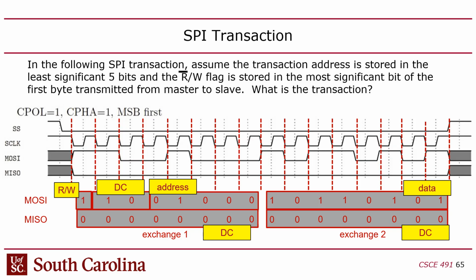In other words, what I'm trying to say is that the ESP32 hardware only knows how to do exchanges. It doesn't know how to do transactions. The transactional behavior is part of the driver, essentially, in the software. It's determined by the software. So the transaction is a software behavior. The exchange is part of the hardware behavior, unless you're bit banging, which is where the software individually controls the bits.